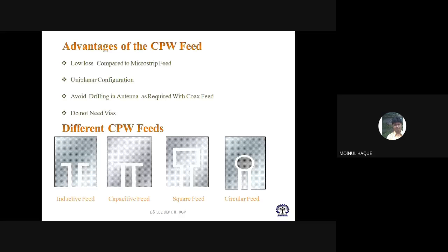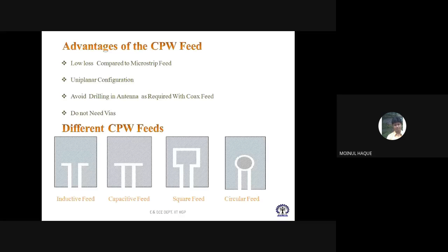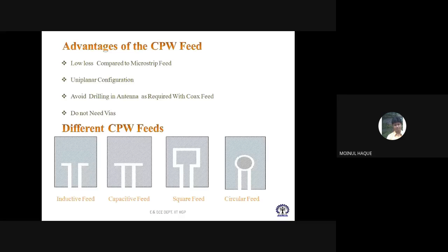If you use a dielectric kind of structure, there are different modes in that dielectric, and only if you excite a particular mode will it radiate properly. So you have to give energy in such a way that exactly that mode is excited. If it is not excited, then the energy will be lost. Instead of radiating the energy, the dielectric material will store it.